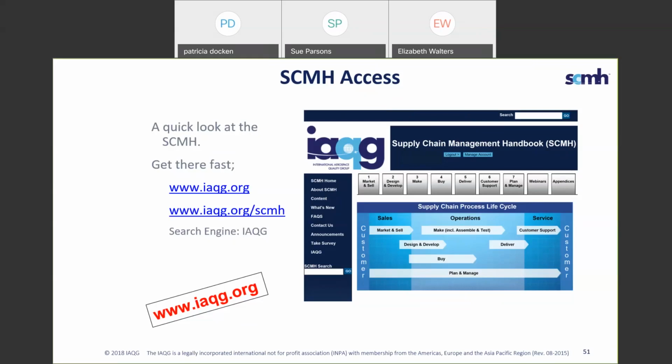How do you know when a PFMEA needs to be done versus just a control plan? You need a PFMEA to do the control plan. That's the best practice, so you can identify risk. What is the risk that you need to look at? What can you poke-yoke out? And where's your variation? You'll have your RPNs, and it's going to tell you what's high. Where are the characteristics? Just to create a control plan, I don't know how good that would be without evaluating risk first.